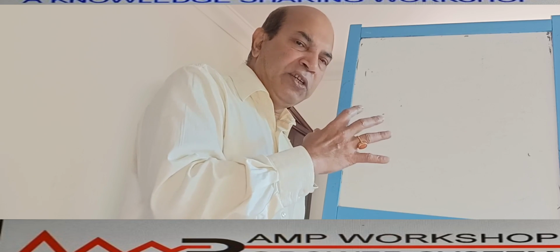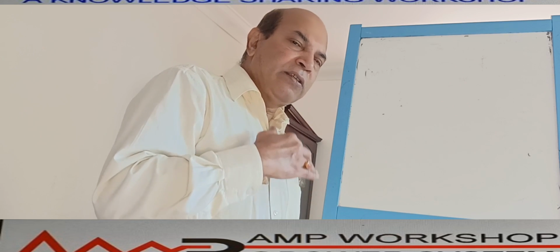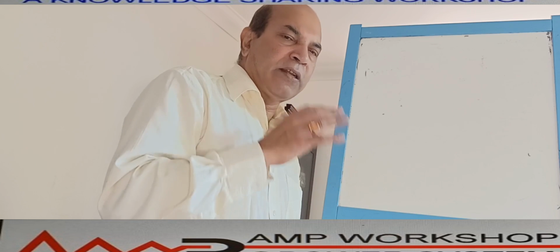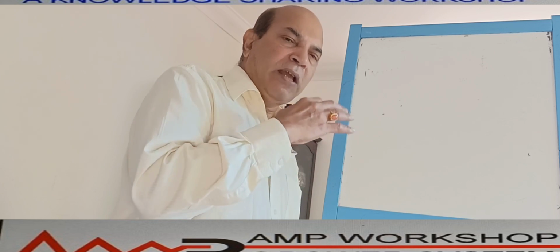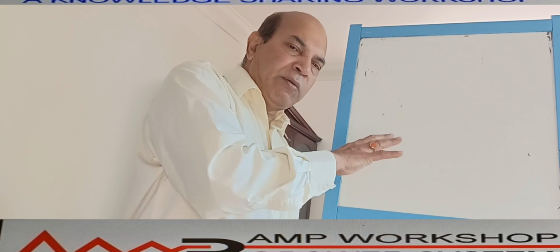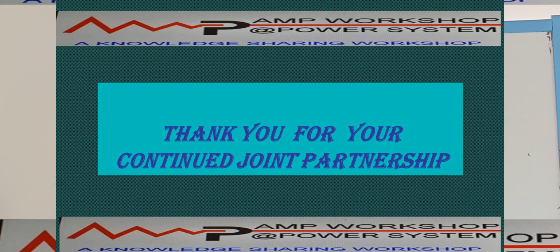But I am reiterating that this is a simple network, that's why we can do the calculation by hand. But when the network is very big, you cannot do this calculation by hand. In that case, you have to go for computer software, and there are many software packages available in the commercial market, like ETAP. Most consultants have this software and training from the software company, and they can calculate the short circuit current using that software. But the basic concept remains the same; only for each software there is a tool for how to do this calculation and how to operate it, for which you need some basic training from that company. Okay, so this is all about the symmetrical short circuit calculation.